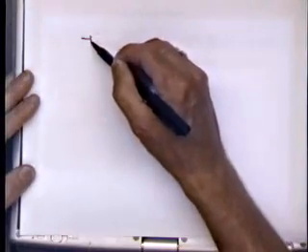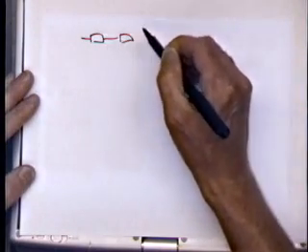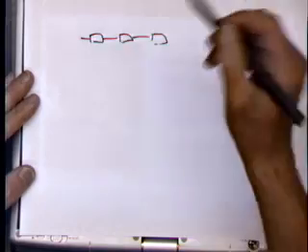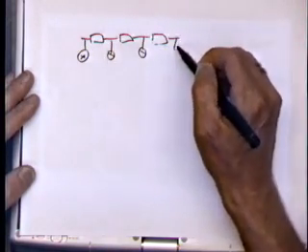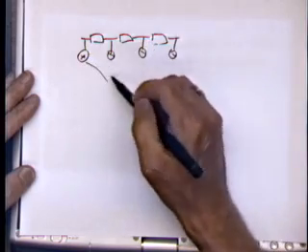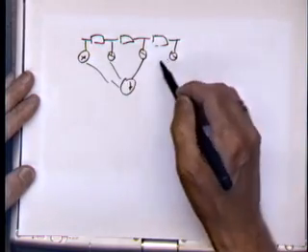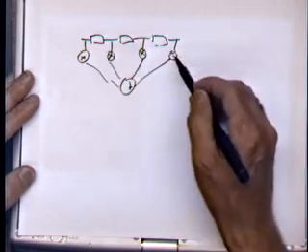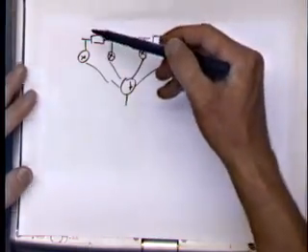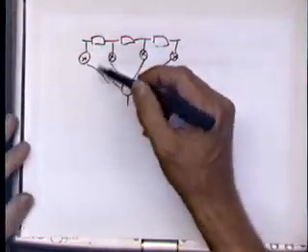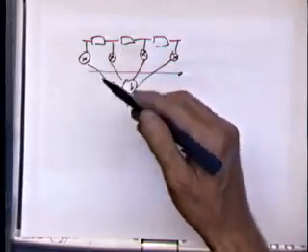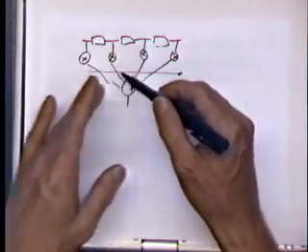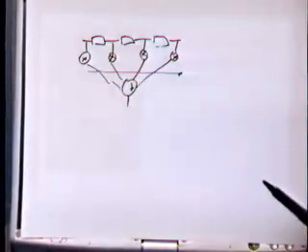If you take an FIR filter, so you have, let me just draw a delay line. This is a simple case. You have multiplies here, multiplies here, multiplies here. This is simplistic, but typically what you would do is add them all together, right? And in general, people start from the first end here and then propagate towards the end. So you have your first multiply, you take the second multiply, add those together, you take the result, move it to the next add, and so on and so forth.